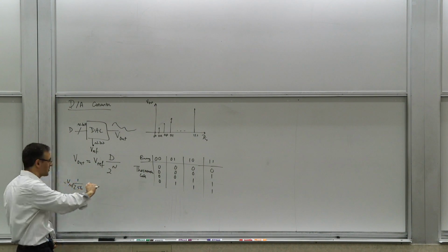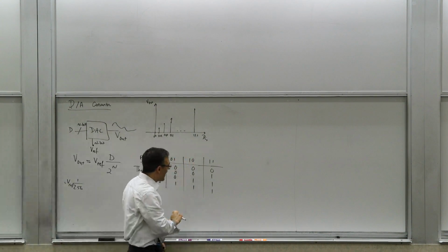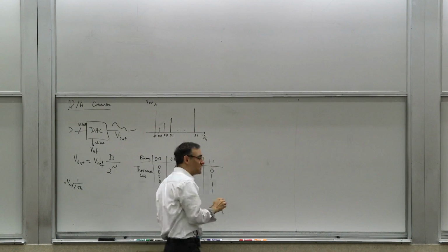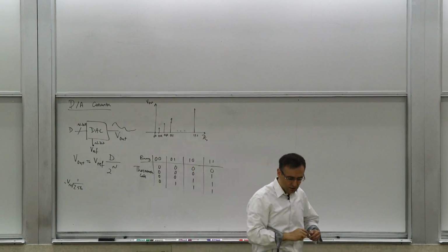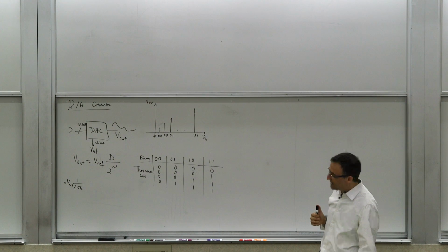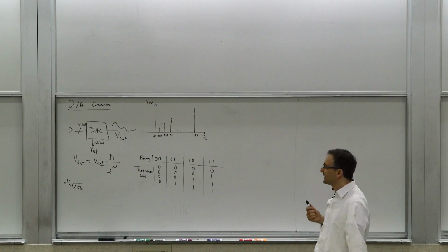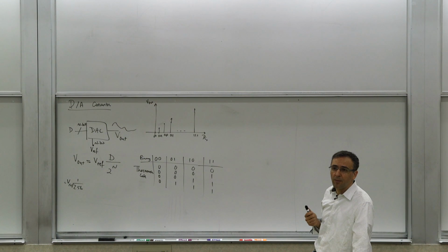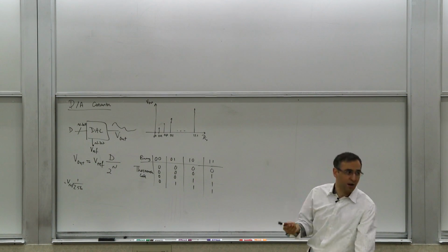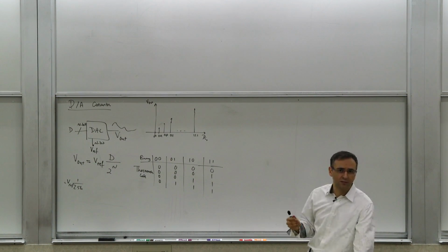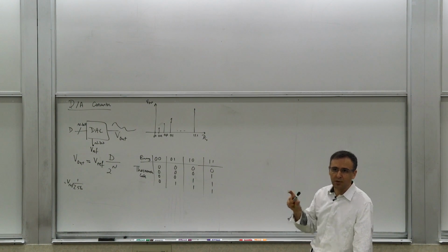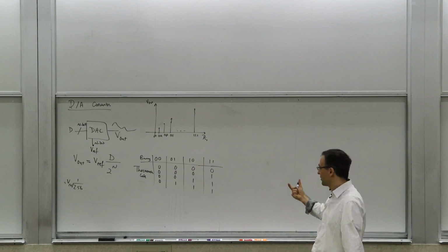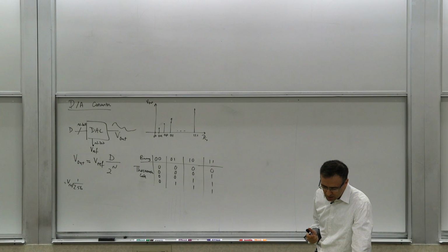It's useful in a lot of applications, as you will see when you're implementing these things, both in digital to analog and analog to digital. A lot of times, not always, it's easier to work with the thermometer code than the binary. There are binary to thermometer code converters, which are digital blocks of combinatorial logic, and thermometer code to binary converters.